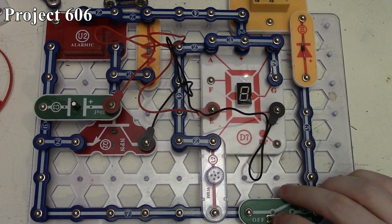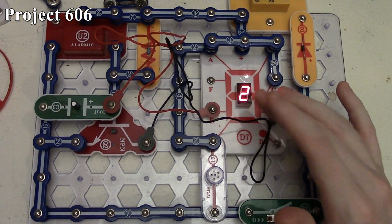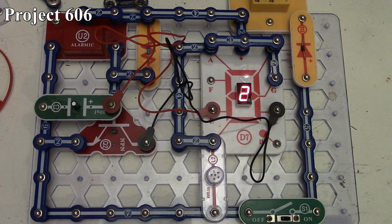So when we turn the circuit on, now it's alternating between showing us a 2 and a 3. Again, as the alarm IC switches and controls our NPN transistor, we get that alternating segment between E and C here, where it will either show us a 2 or a 3 as the circuit operates.